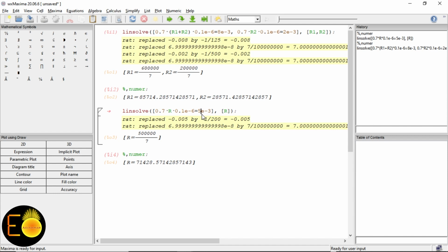I'm going to set the output frequency to 10 kilohertz. If it is 10 kilohertz, then the total time period is going to be 10 to the minus 4, and here I can set for the half period it should be 10 to the minus 4 times 0.5.